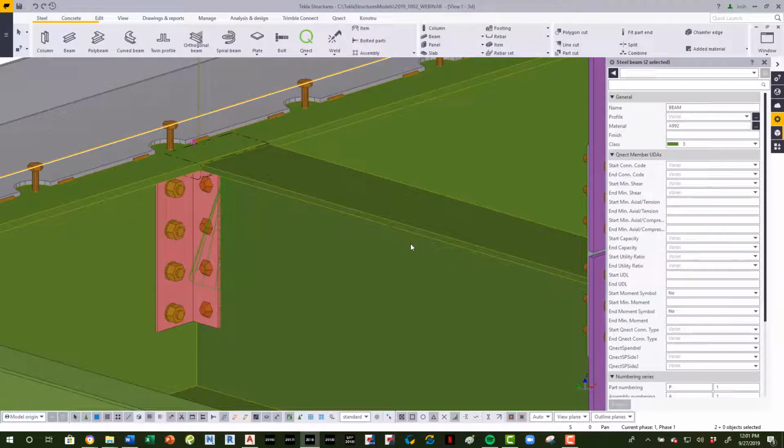All right, so we went from 6 rows to 4 rows. Okay, so now we have 6 less bolts overall. So that means 6 bolts we don't have to order. That also means 2 fewer bolts in the shop to install, as well as 4 bolts fewer to install in the field. So 12 holes less to drill, cut, or punch on one connection. So 33% of that connection with the bolts is just gone. So what does that really mean to you?